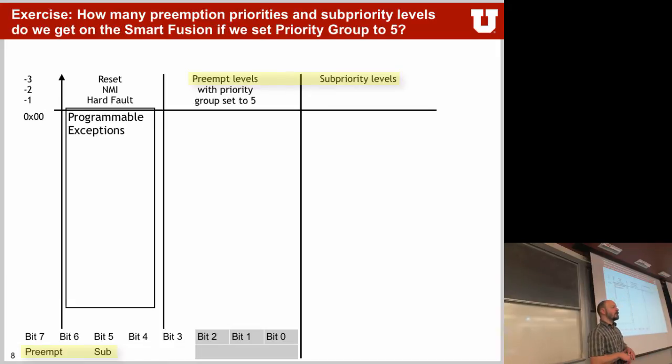It turns out that a vendor does not have to implement all priority levels because that generates a lot of logic in the background. So oftentimes they opt for only fewer bits. Then the lower bits are just static zeros, and only the upper bits get used for the different priorities. So in this case, we have 5 bits in the top and 3 bits at the bottom. These 3 bits will never be changed, and these we can use for programmability.